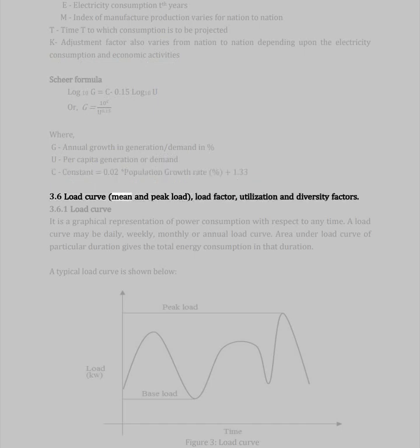3.6 Load curve, mean and peak load, load factor, utilization and diversity factors. 3.6.1 Load curve. It is a graphical representation of power consumption with respect to time. A load curve may be a daily, weekly, monthly, or annual load curve. The area under the load curve of a particular duration gives the total energy consumption in that duration. A typical load curve is shown below. Figure 3, load curve.